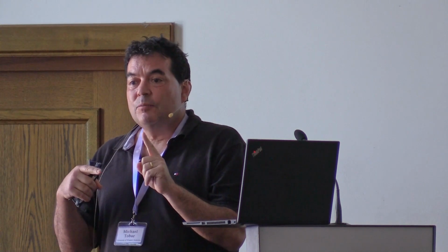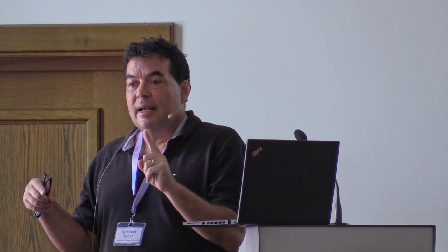Equilateral is really important because you have to have degenerate TE and TM modes for this to work. As you twist it, the TE and TM modes couple together and the basis set changes. It changes from them being individual to being plus or minus, which is plus helicity and minus helicity. And so what you get is one tunes one way and one tunes the other way as you change that twist angle. So I don't know if that answers your question, but that's what happens.